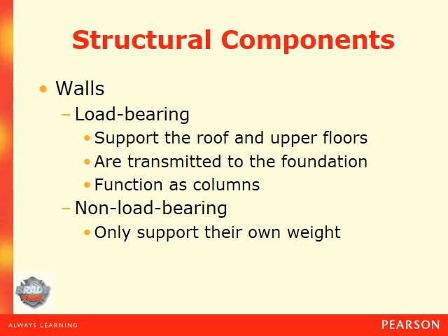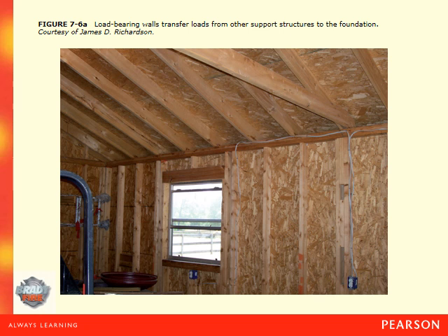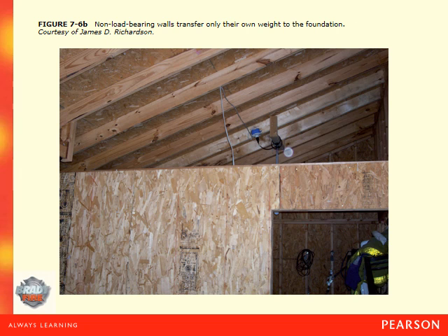Walls. You have load-bearing and non-load-bearing walls. Load-bearing walls support the roof and the upper floors, and those loads are transmitted to the foundation in terms of weight. They function as columns. Non-load-bearing walls only support their own weight. So it's kind of like a wall that divides a room from other portions of the house, but doesn't support the roof. So you could take that wall out and the roof would not collapse. As seen here, this is a load-bearing wall. This is a good example of a non-load-bearing wall.